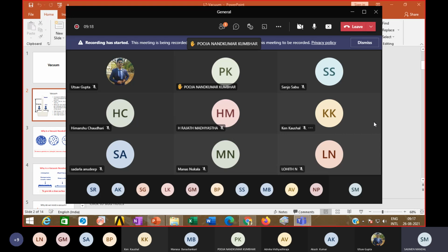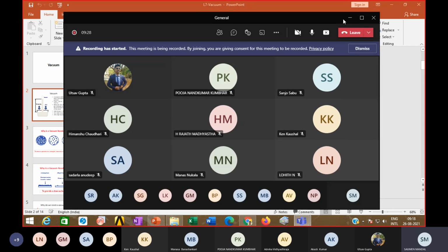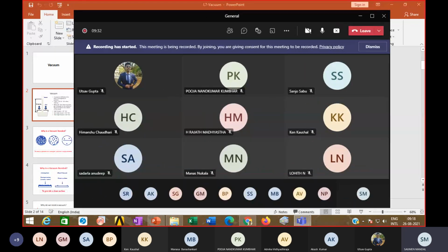So this EDS as well as XPS, these are elemental analysis methods, and XPS is a little bit high-end elemental analysis. It is often used in material science. What information can we get? We can get what elements are present, and we can get what bond formation there is, let's say in oxides. If some defect is there, we can quantify how much amount of point defects there are.